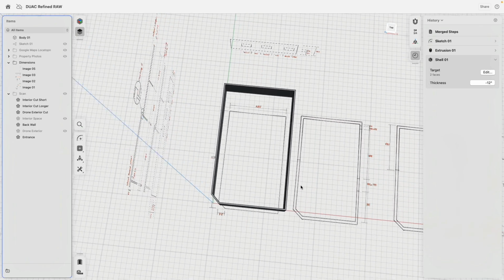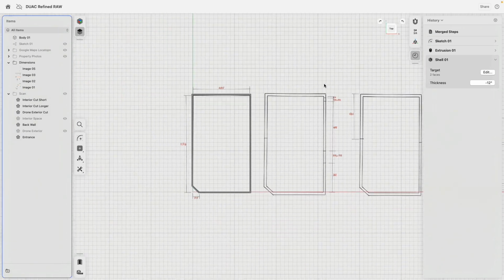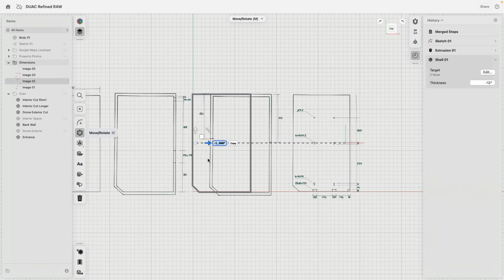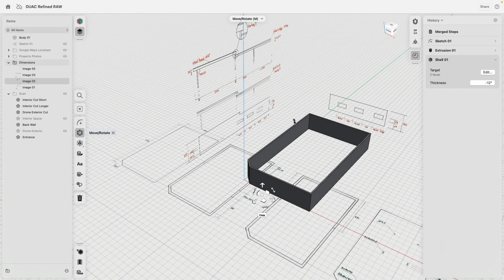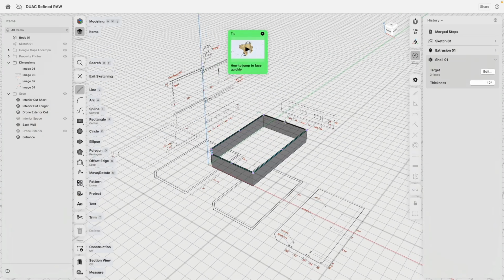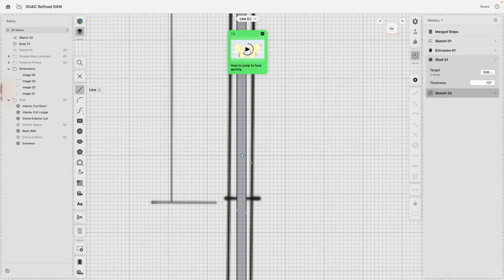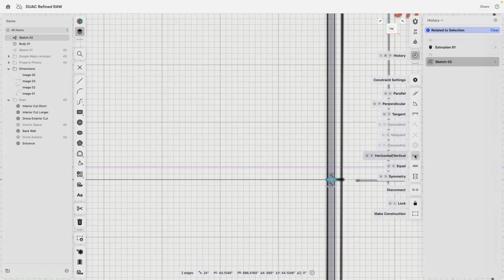So then we can actually maybe do this. I go to top view. I select the plan image, drag this over, because there are two lines. This is where the wall actually goes a little bit higher. So on this top face, that is where I need to create a sketch. There we are. I draw here a line and I draw there a line from edge to edge. These lines will be horizontal, vertical.